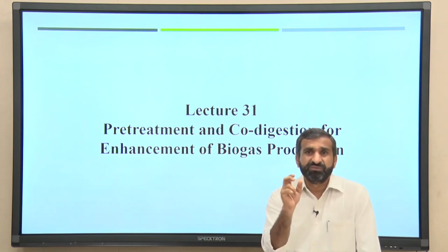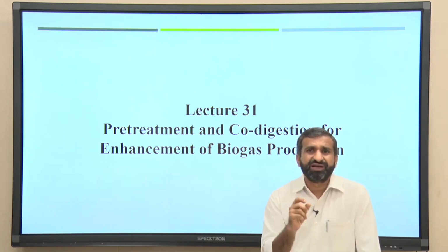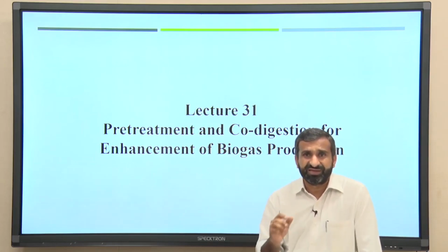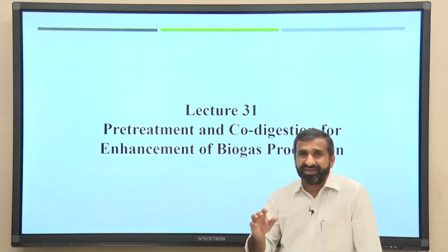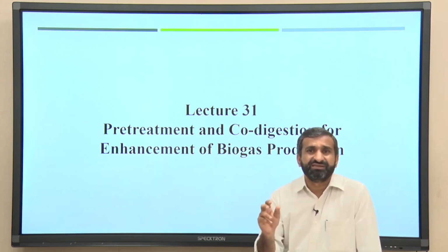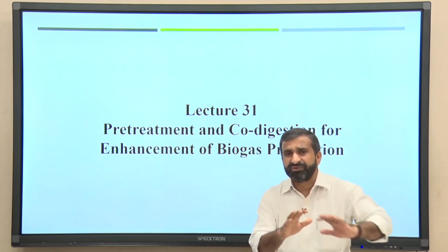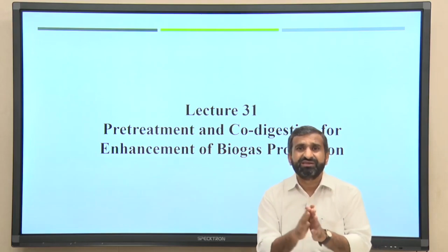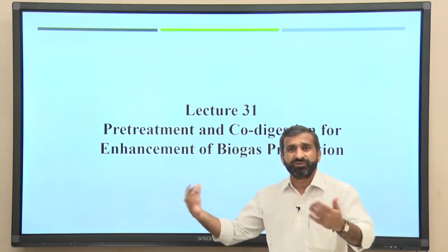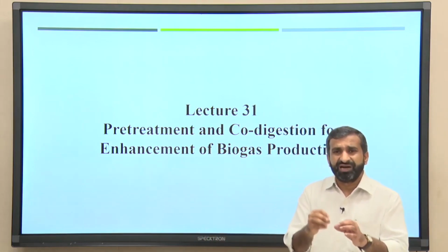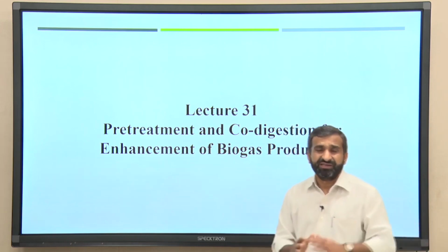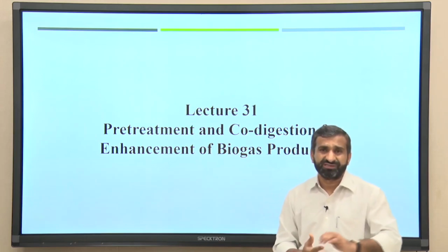And if you see, the major stage is the hydrolysis process, which is the important one, and without this hydrolysis it is very difficult to go for the acid phase or methane phase. In this lecture we will talk about the hydrolysis process, which is the rate limiting stage. If you do not have a proper hydrolysis stage, it will take a longer period for the entire anaerobic digestion process, which means the hydraulic residence time or HRT will be very high.